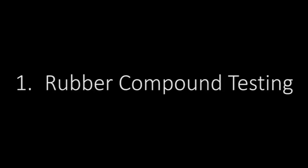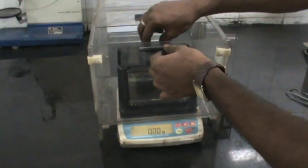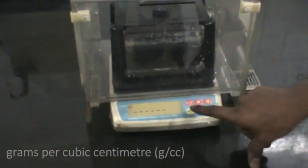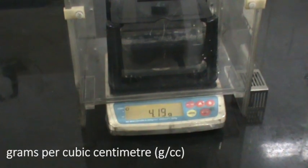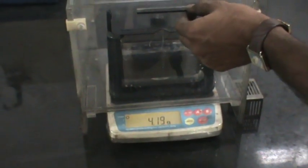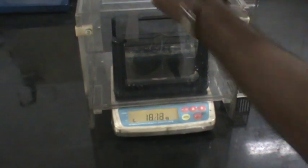1. Rubber compound testing. A. Specific gravity. The specific gravity of a rubber compound refers to its density. This is a measure of the mass of the rubber divided by its volume. The units therefore are typically quoted as grams per cubic centimetre, g/cc. This merely indicates the weight of the rubber and is useful to identify the purity of the compound.